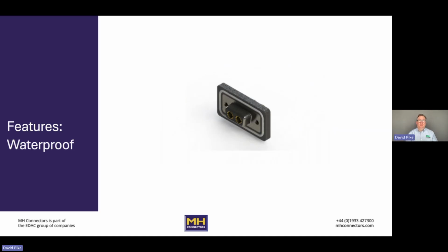There is another side of D-sub, which may surprise some, is that you can actually make D-sub connectors waterproof. They weren't designed originally for this, but with a little bit of clever engineering, D-subs have been made available with these sealing flanges around the outside of the connector. This allows the connector to provide a panel mounting option that's protected up to IP67, IP68 in some circumstances.